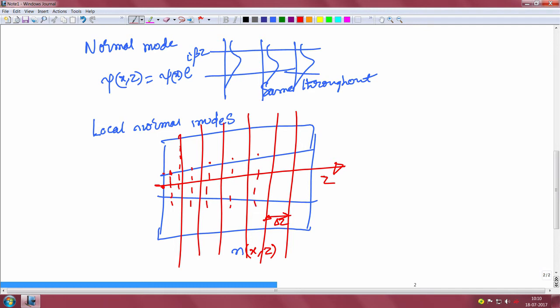and then assuming that the waveguide is straight in each of these sections and knowing that the propagation is defined as e power i beta z, we can obtain the field propagation characteristics at every segment and then obtain the useful propagation characteristics.